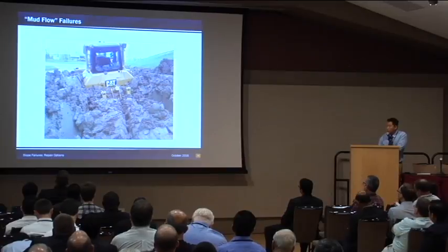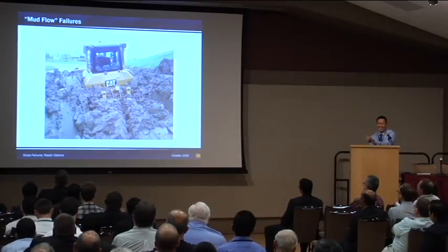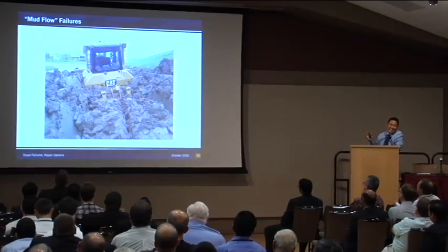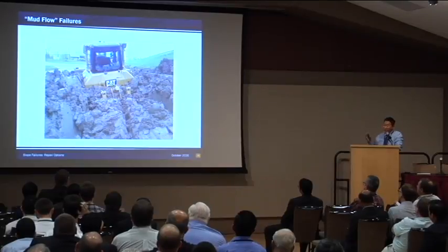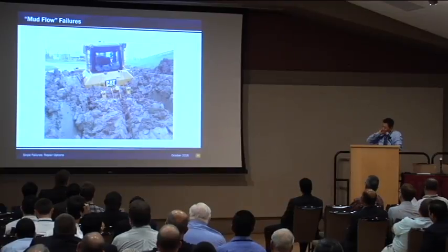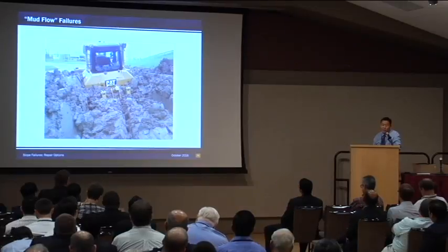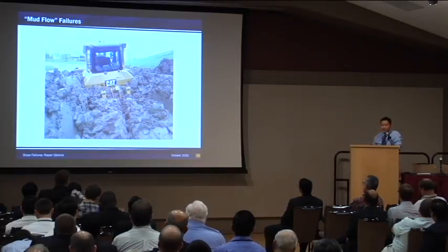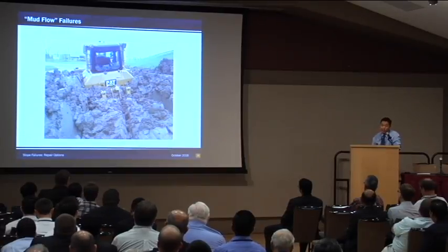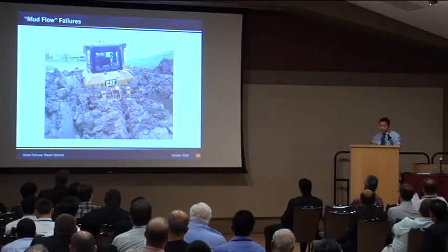So yeah, this is not good at all, right? This is the indication of how bad the embankment material is. It is a very high PI clay. The plasticity index was actually tested by Texas A&M, as we installed one of the monitoring instruments as a part of the research project. The PI, as I remember, is like 65 to 70-ish, which is a very high PI, and it performed okay for about 15 years, and then it failed.